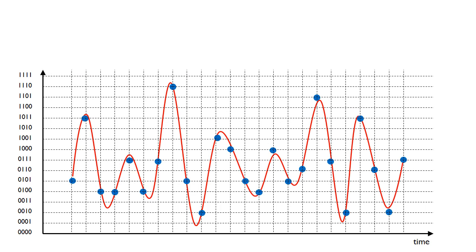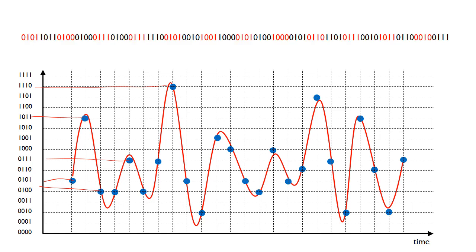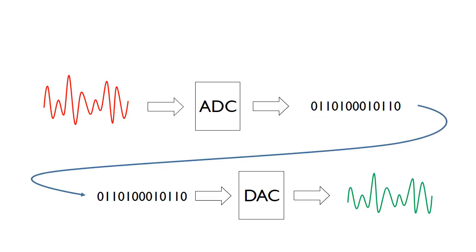We've seen examples of how we use these before. The red line here represents our analog signal changing over time, and then we sample this signal at discrete points in time, and each level is represented by a binary value. By reading those values at these discrete time points, you can build up a digital version of that signal, for example, which we will then transmit.